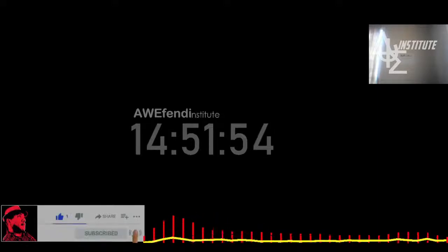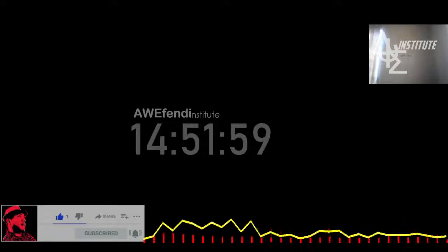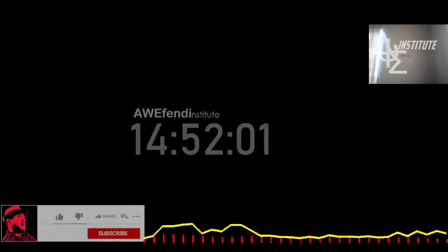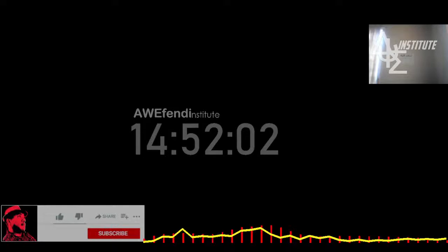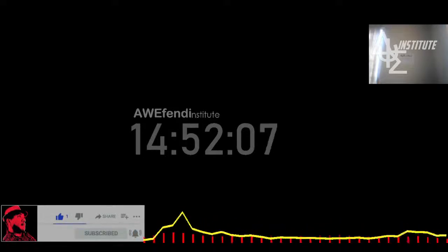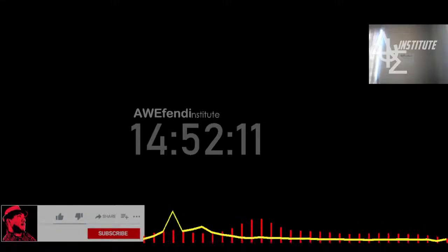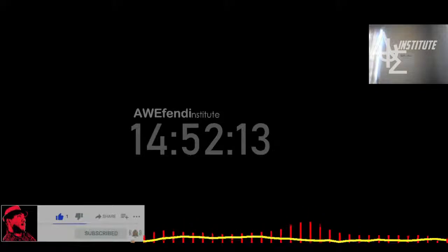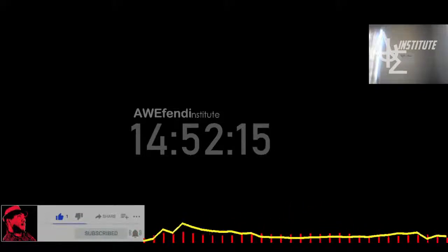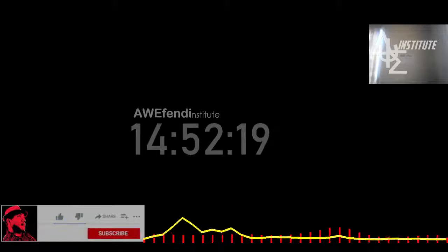We can also make use of monitors. If we plot the monitors, we can see the monitor of the maximum temperature, which we can assume is always found in the CPU because that's where heat is generated. And so we can use it as a proxy for measuring our temperature. And we want this to be below 70 degrees. And now everything is fine because it's 45 degrees. So everything is working well. Our CPU is within the acceptable range.